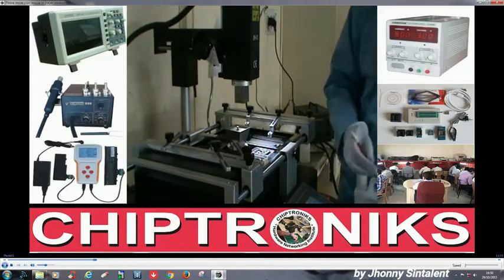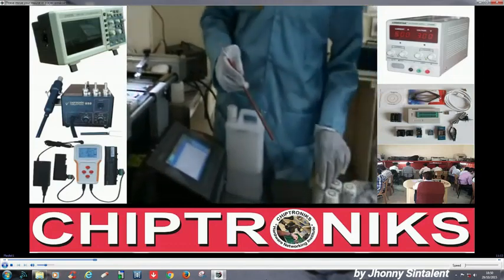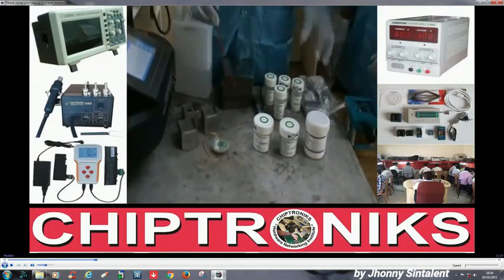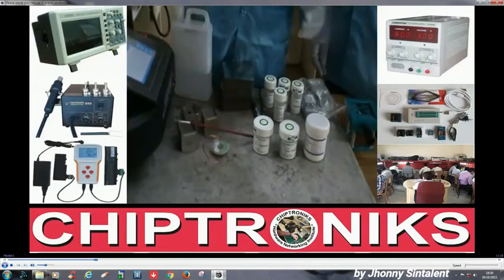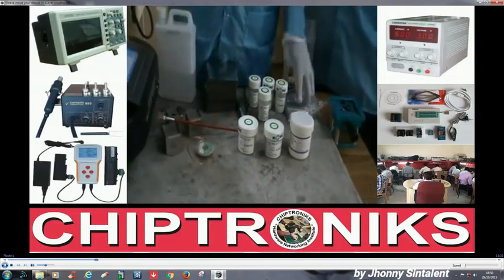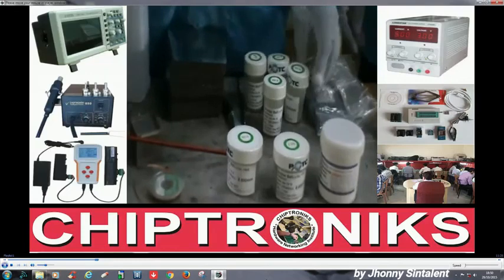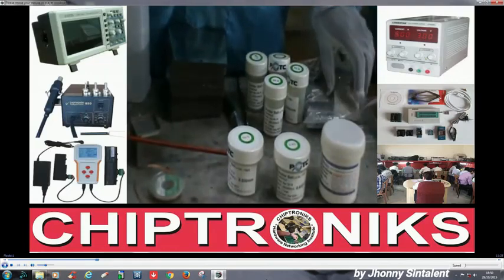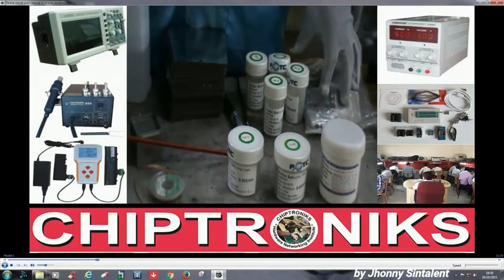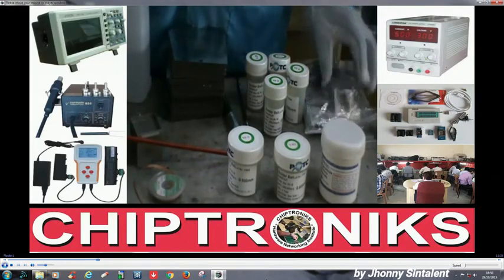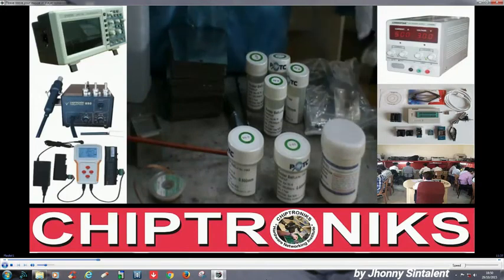And apart from solder balls, you require a stencil set for making balls, and there are 2 types of stencil set in the market. One is the direct heat stencil set, having a size of 80 by 80 mm. This is smaller in size, but that is direct heat. Direct heat means you can put heat directly on this stencil and it won't bend up.